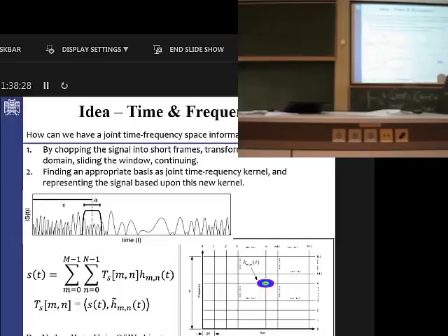Or you want to reconstruct the signal using atoms, the bases, which are not as simple as what you use in the frequency domain, e to the power of j k omega. They are combinatorial or complex atoms which contain both the time and frequency information at the same time. They are called joint time-frequency atoms, h_mn in the discrete domain.